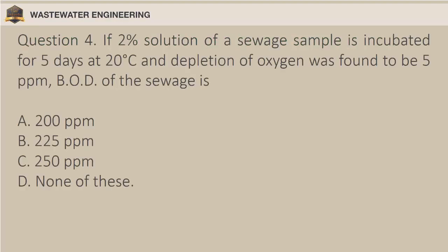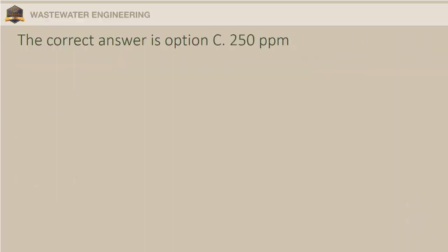Question 4. If 2% solution of a sewage sample is incubated for 5 days at 20 degrees Celsius and depletion of oxygen was found to be 5 parts per million, B.O.D of the sewage is A. 200 parts per million. B. 225 parts per million. C. 250 parts per million. D. None of these. The correct answer is option C. 250 parts per million.